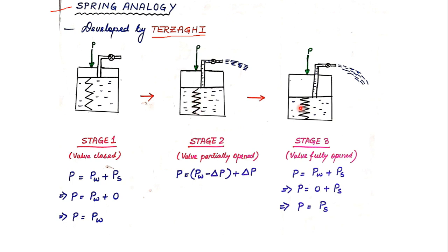And when the water has been fully drained out of the soil mass, the entire load will be taken up by the soil and it will be fully consolidated, or we can say that the volume has been fully decreased. So this is the process of consolidation from Terzaghi's point of view, and since this is compared to spring and water, it is known as spring analogy. Alright,